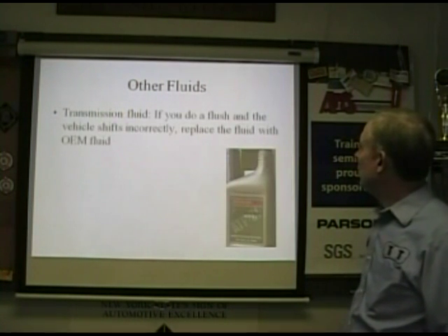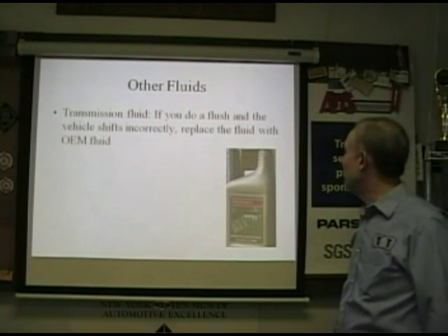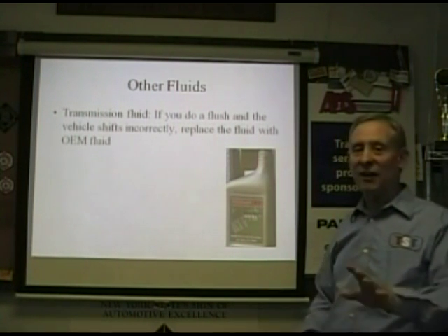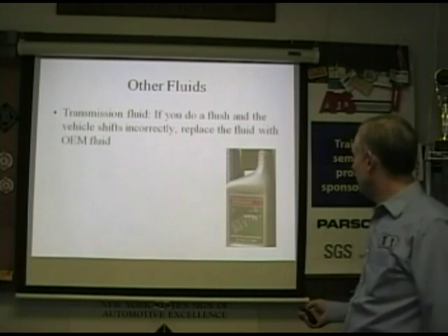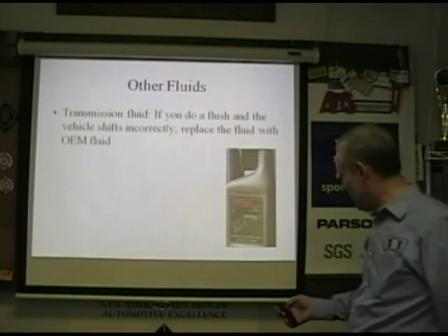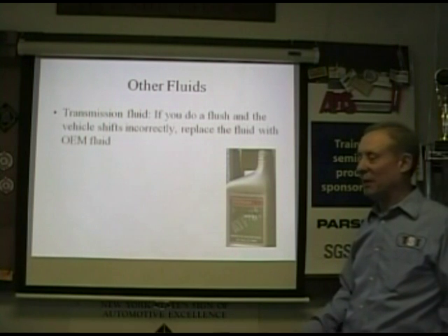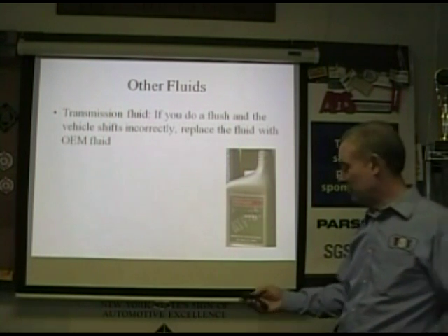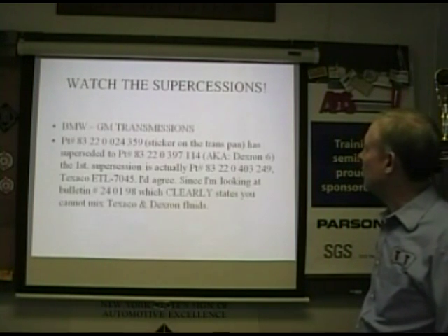All right, transmission fluid. If you do a flush and the vehicle shifts badly, put in the OEM. If there's any kind of an issue, put in the OEM. If you're not sure, put in the OEM. Is that a Honda bottle up there? Honda Genuine HG. There you go. Jerry's just mentioning it, Honda Genuine fluid. They bang you for some money, but as a professional, you've got to put the right stuff in. And you mark it up. You get whatever your discount is. You've got to do the right thing.